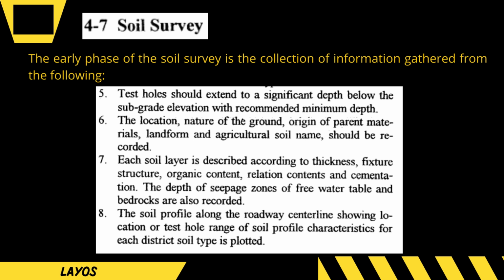And each soil layer is described according to thickness, texture, structure, organic content, moisture content, and cementation. The depth of seepage zone, free water table and bedrock are also recorded. And the soil profile along the roadway center line, showing location of test holes and range of soil profile characteristics for each distinct soil type, is plotted.